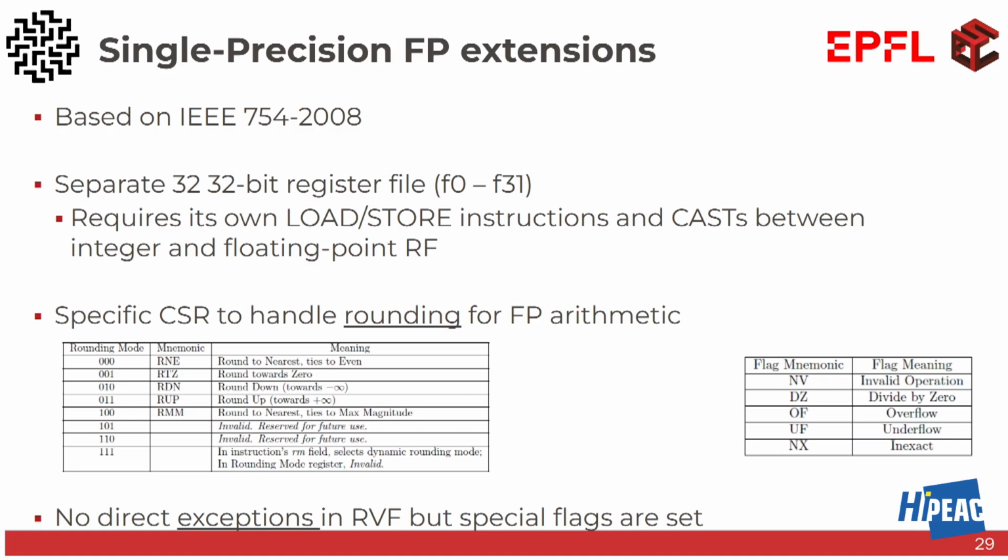Dedicated instruction. A dedicated instruction, or? On what level are we? Like, sure, it can be a dedicated instruction, yeah, but I'm asking how you guys will do it. There's no right or wrong answer. They're both correct, right? He decided to spend an instruction to do that. He decided to use 2 instructions to do it. RISC-V decided to do like he proposed, having a dedicated load and store instruction that are called fload, fstore. Easy. Okay? Whenever the CPU gets an fload, it knows the destination is the floating point registers.